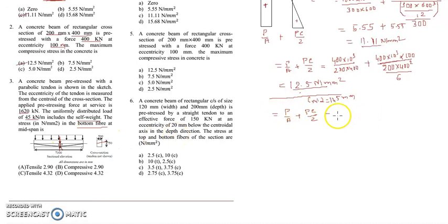to be under tension. So this is going to be MD by Z minus ML by Z. So what is MD and ML? They are not given separately, because the live load is also a uniformly distributed load, and the dead load is also a uniformly distributed load. I can combine them. So therefore the moment is going to be given by how much?